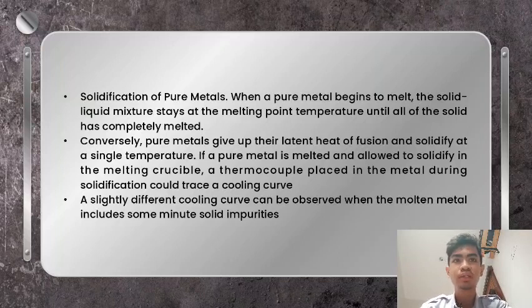During supercooling, the freezing process is arrested because not enough heat of fusion is released from the liquid to sustain the transformation from liquid to solid. When solidification does begin, the temperature recovers to the melting point temperature and remains constant until the metal has completed the transformation to the solid state.